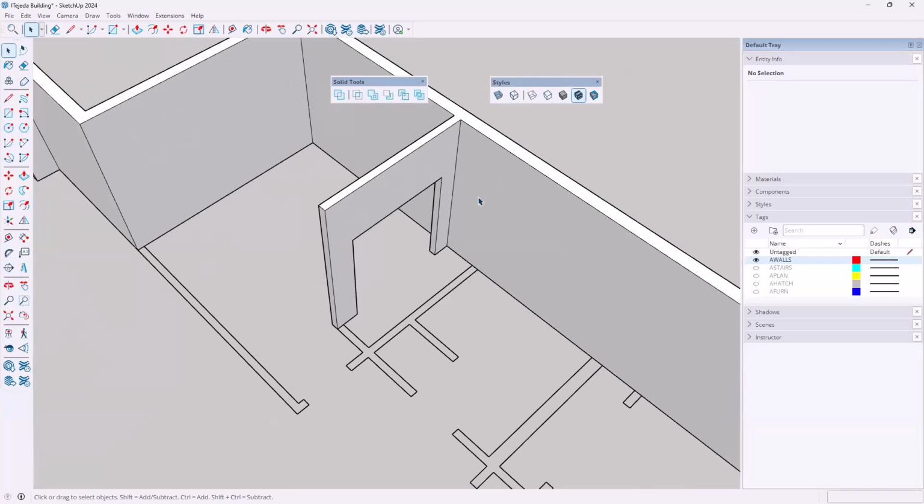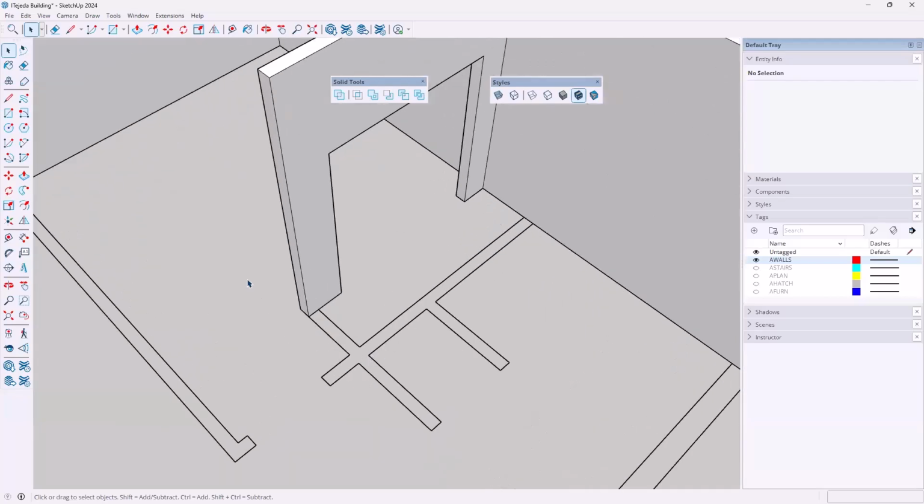So let's say I'm not in the group purposely, and I want to finish modeling this set of walls over here. So I'm going to come in, and whatever technique, whether you draw the lines to create the surface, whether you draw multiple rectangles, however you want to do it is fine. I'll just go ahead and type L right now for line, and I'll start drawing a line from here, going across, and then just tracing the line work that's there.